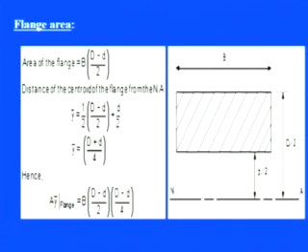So with the consideration of these two different sections, we can again calculate the distance of the centroid from the neutral axis, which is y bar equals half of this area of the flange which we calculated, D minus d by 2, plus d by 2, because you see here somewhere it is exactly exerting on this. You can see this diagram. So half of this height, D minus d by 2, plus this distance d by 2.